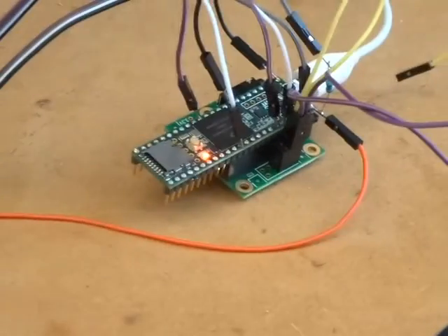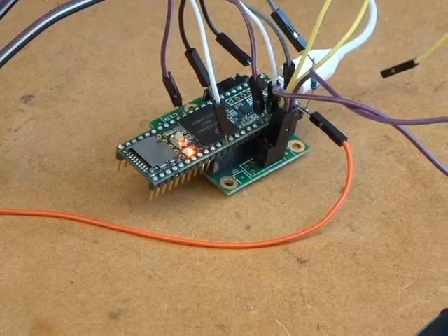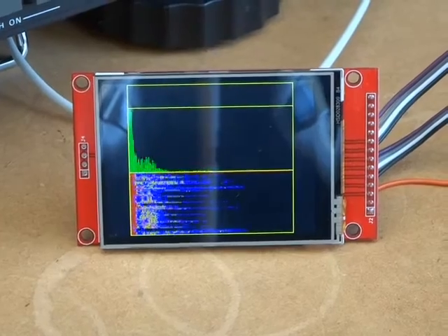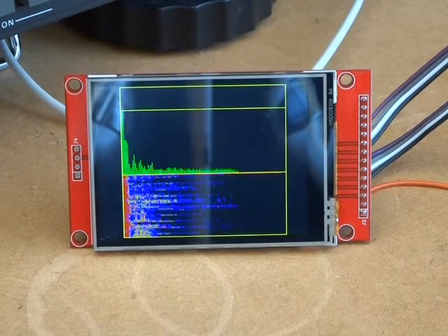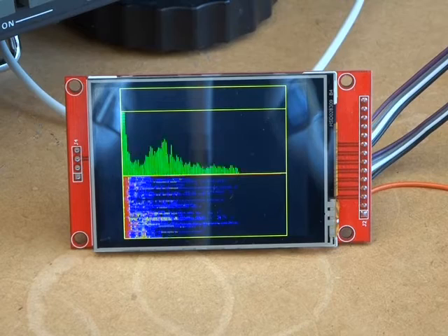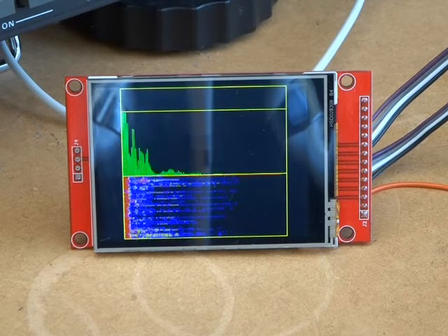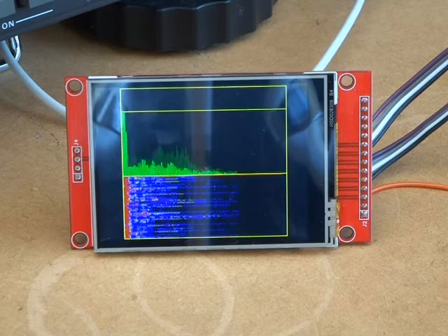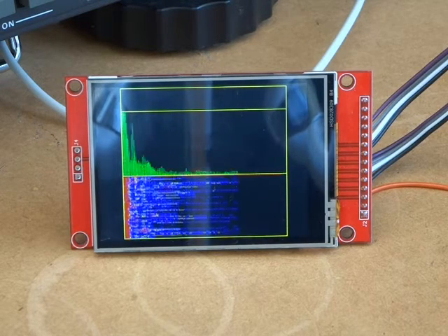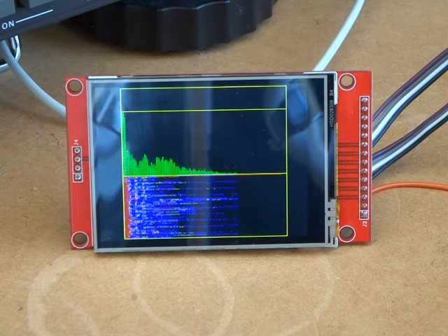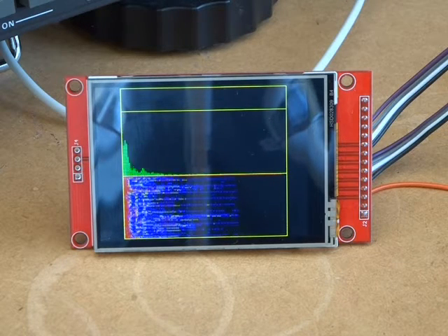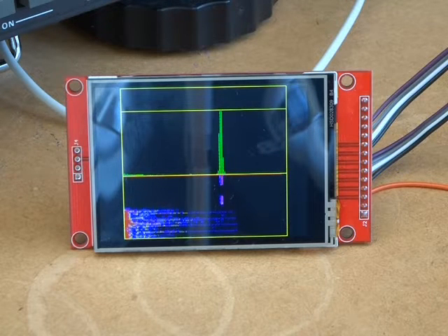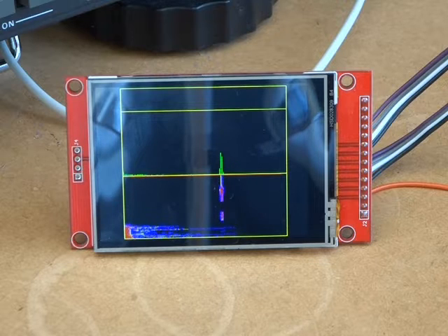That's currently plugged into and wired into the Teensy 3.5, and I'm just utilising the FFT analysis tool sitting within the audio library, which again we'll have a look at there. At the moment that's just listening to some music, and if we were to change that to a SIGGEN or an audio generator, then we can see there just a signal coming through at 15 kilohertz.